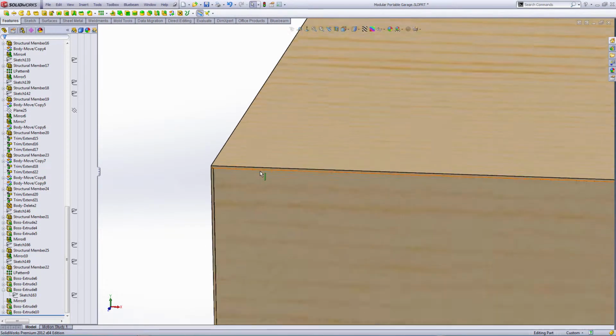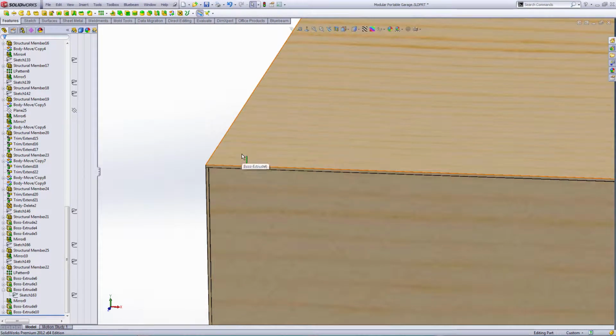I would also come back and add curbs to this, just 2x4s to the roof, and then I'd probably use a Duralast membrane roof. I would put the curbs on with screws, so if you ever add a second story you can pull them off easily enough. And then Duralast sells what they call a turn bar, or whoever the membrane roof manufacturer in your area is, they have what's called a termination strip, and you can fasten the roof to the walls with a termination strip. And I would also probably put internal drains in, but that's up to you.